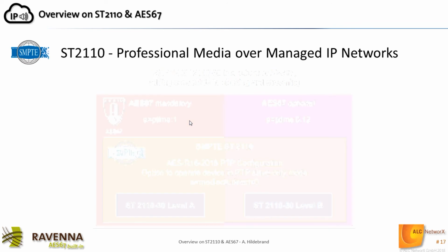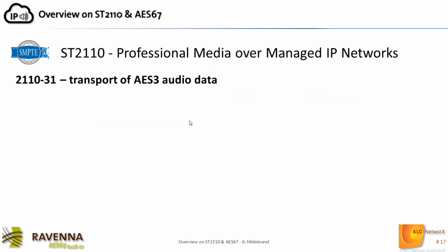So now folks were worried about what if I want to transport an AES3 or AES-EBU audio signal. So that is the metadata which is part of the AES-EBU signal definitions, which can be transported with the full AES3 audio line. Plus, how can I transport nonlinear audio formats such as Dolby E, which requires more than the 24 pure PCM audio bits?